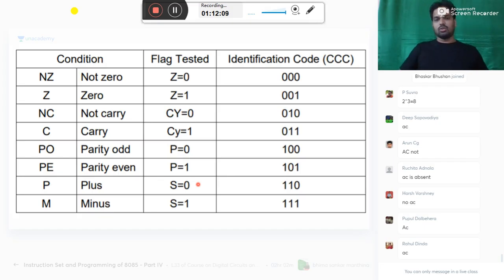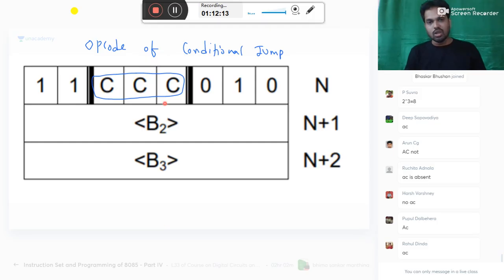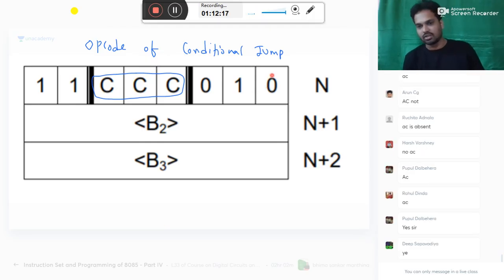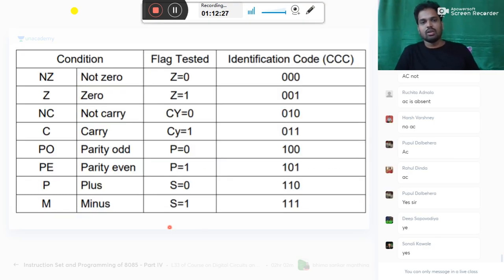Do you understand now? Because you have only 8 bits for opcode, only 256 combinations are possible. In that only you should adjust everything. So any conditional jump is not available with auxiliary carry. It is less frequently used. The examiner, we always get the examiner in our mind. The designer has neglected that.